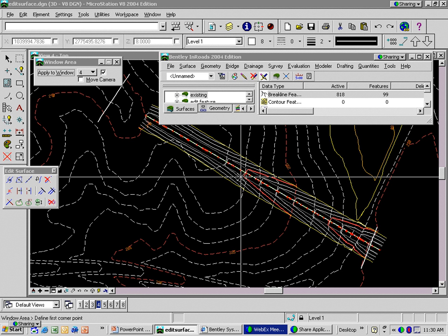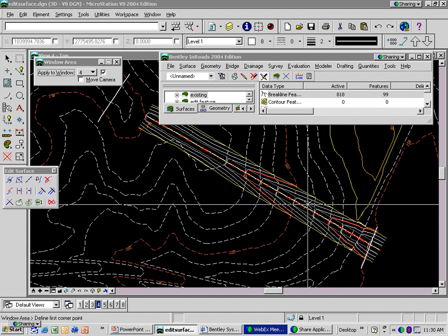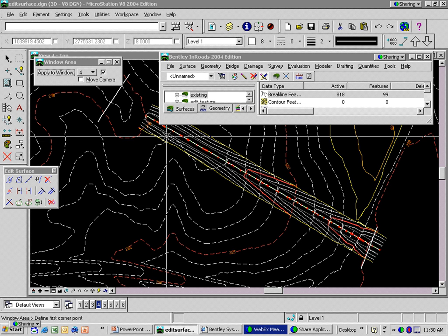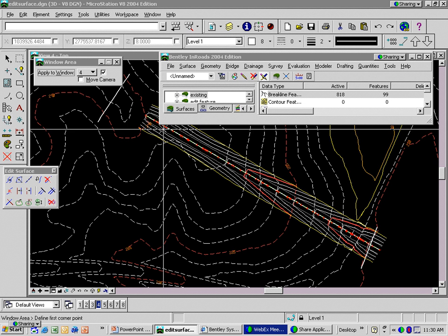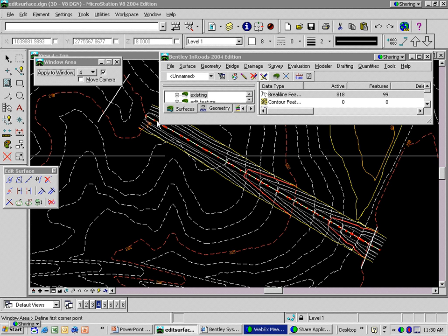So what we're going to do is we're going to first go to extend feature. This is a different surface, so we're going to go to our channel. We get choices for elevation. We have do not change. In our case, we want to match the existing where we drape the line on the existing surface.